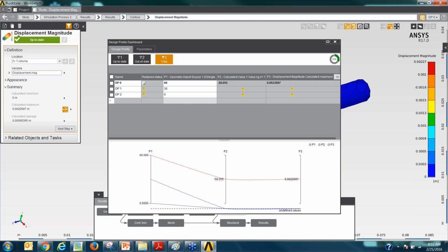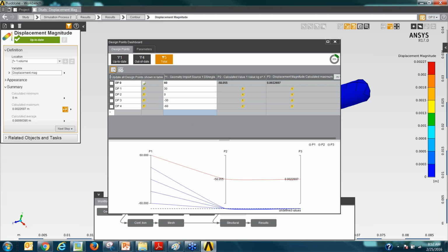For a 0-degree angle, that's going to have very little separation, obviously, right? If that valve is at 0 angle, maybe minus 30, minus 60, and then if I click on this button, it's essentially going to update all the results, including these values. So like I mentioned earlier in my presentation, design optimization, exploration, running what-if scenarios, that's huge when you use any FEA tool, and AIM has that built into its workflow template there, okay?